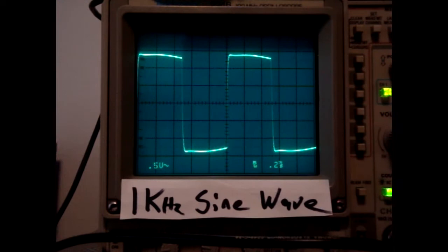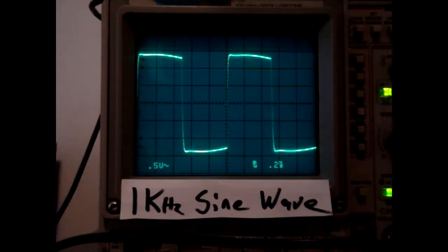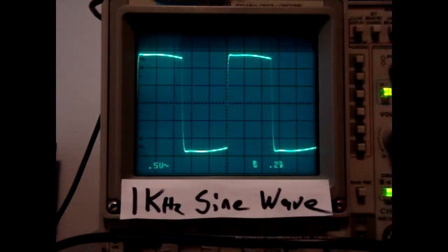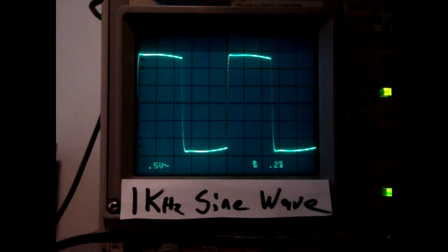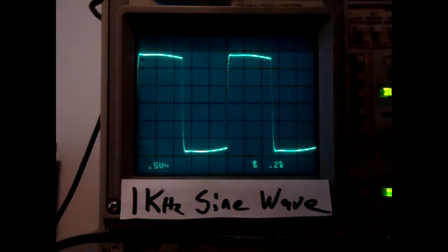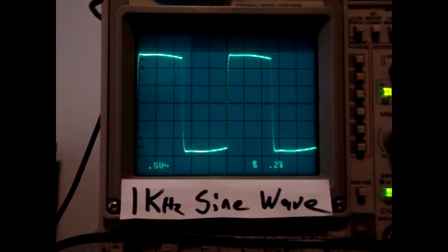It tells me it's neither boosting nor cutting any frequencies, and I can get an accurate analysis of the response of the amp. I've seen tube issues and things like that that'll cut the bass frequencies, and you'll have nothing but a high-end response. You'll still hear audio, but it sounds like crap. And that's one of the uses of this kind of thing.